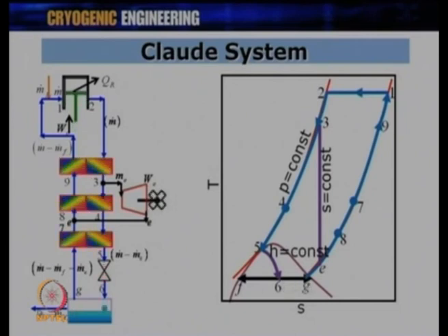Here the M dot F is collected from the container, and the return stream would therefore have M minus Me minus Mf. Okay. So, out of the gas M which is compressed, Me is going to be expanded through the expansion engine, and it joins here at point E. What is going to come ahead beyond this point is M minus Me, out of which M dot F is collected. So, what is remaining and going back in the return stream is M minus Mf minus Me. This is very important because we have to understand this in subsequent slides. Okay, so, the gas which is going back is M minus Mf minus Me, which is at point G, which is a gas over here.